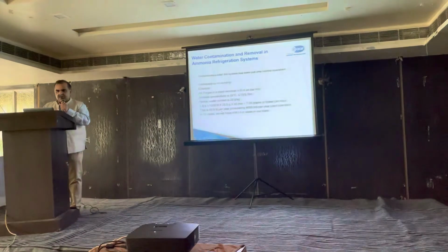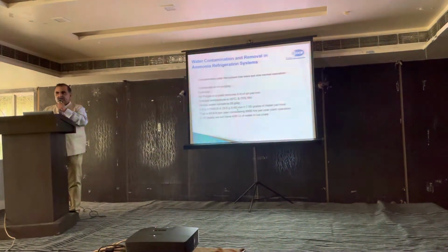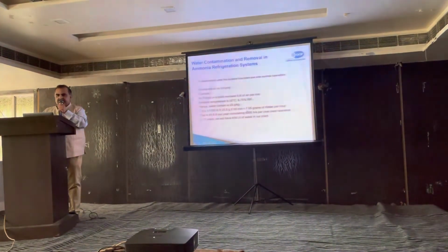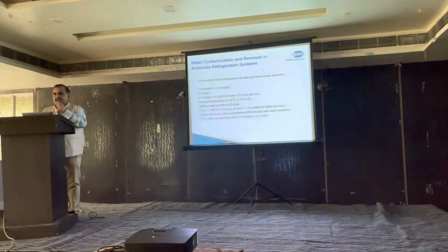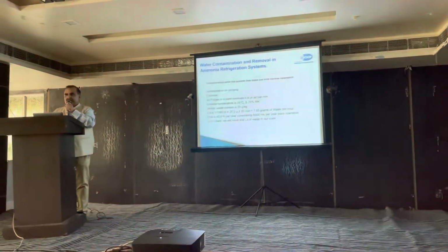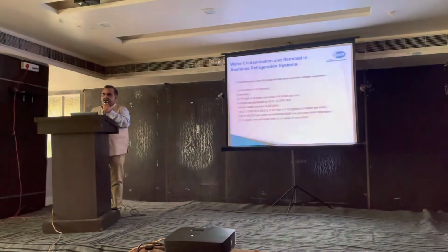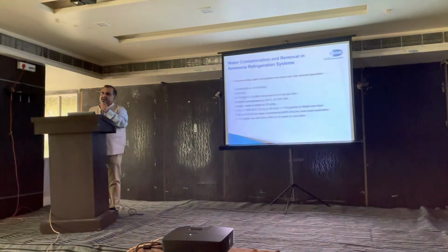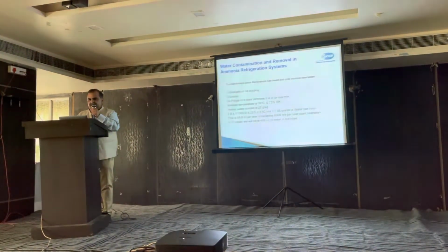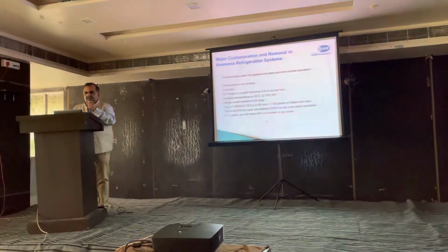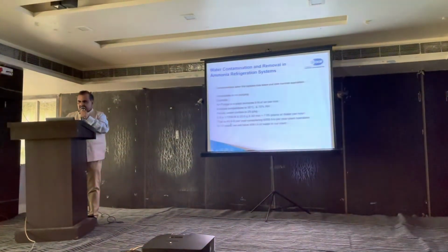So when we are talking about the air purger removing air for 1 hour, it means that we are also getting 7 grams of water per hour in our plant. When the air purger is continuously removing air, it means the air is continuously entering our plant somehow. It also indicates that water is getting into the plant. So if we are having just 5 liters of air being removed, we are talking about accumulating 45-50 liters of water in a year, which will not be removed.